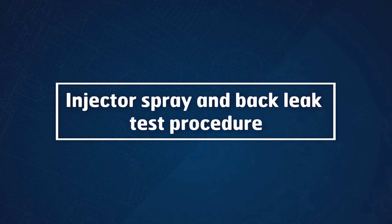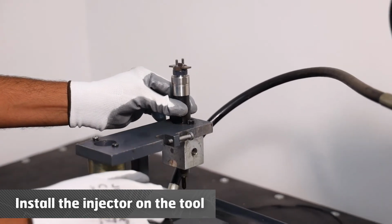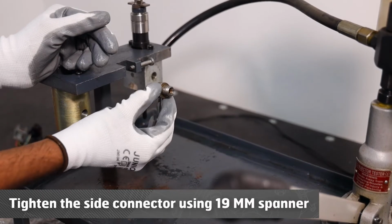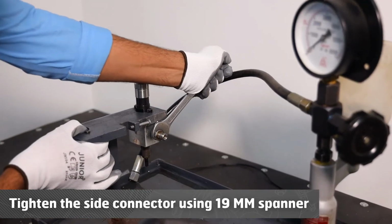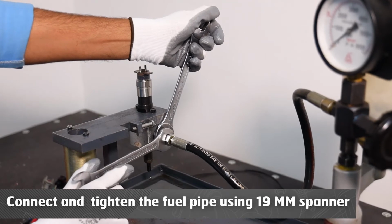Injector spray and back leak test procedure. Install the injector on the tool. Fit the side connector and tighten using 19 mm open spanner. Connect the fuel pipe to the injector and tighten using 19 mm open spanner.